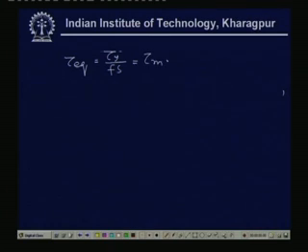So, tau m plus, I hope that you understand what I am writing, because this we have already discussed, that equivalent concept. So, Fs, again you see we are multiplying only the stress amplitude part, but not the other thing. Other thing means the mean stress.